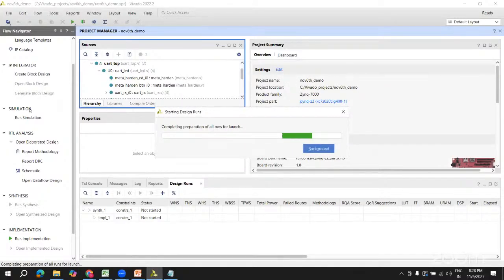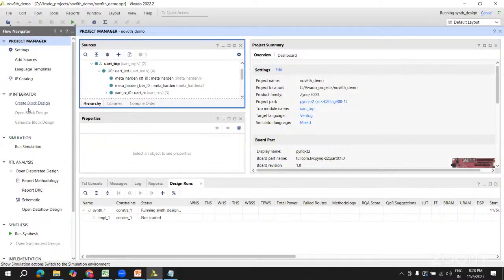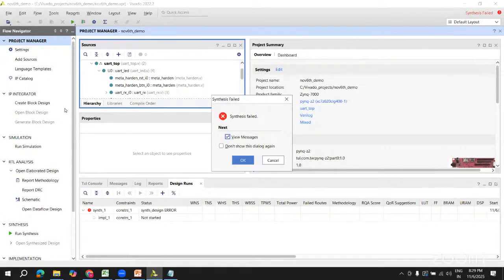Right. Okay, let me run synthesis first. But before we do this, as I've told you, there are multiple protocols and multiple sequences that the Vivado tool uses in combination with your FPGA, right? Depending on which architecture you're using and which FPGA you're using, your tool will be able to decide what are all the available resources for me and how do I customize these particular resources for my usage, right?